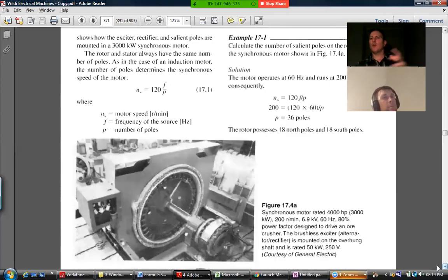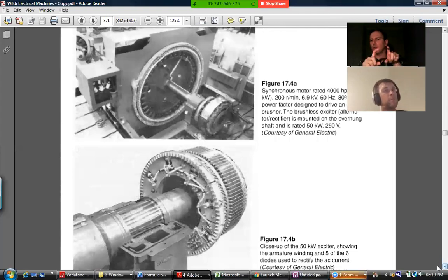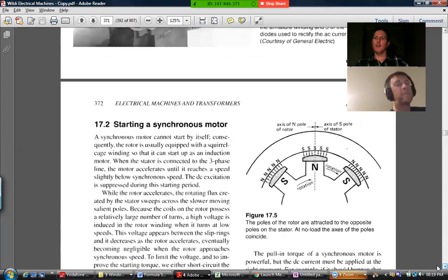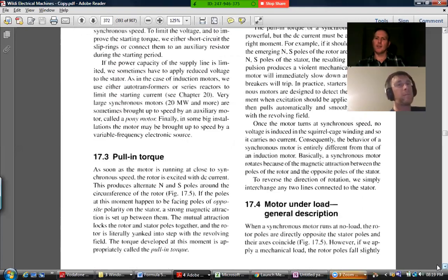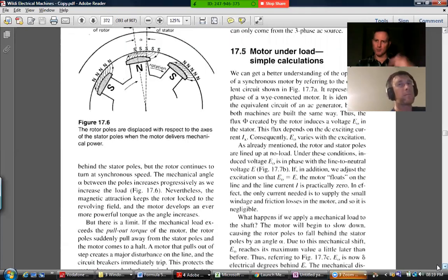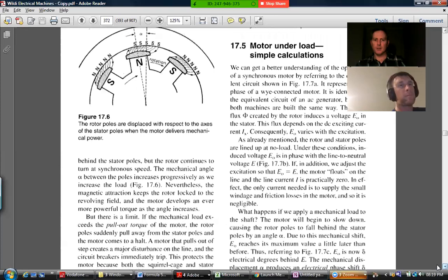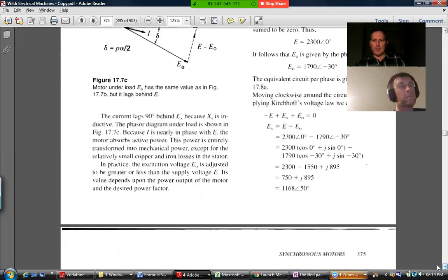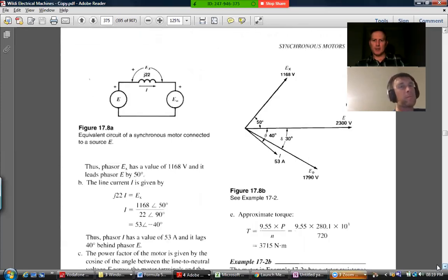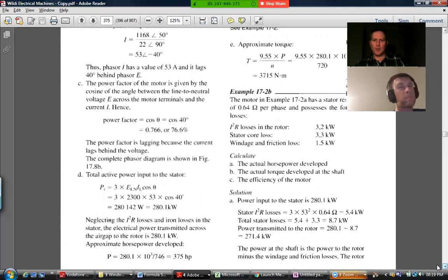Most small synchronous motors will just have 2 slip rings ready for you, and you just feed your exciting current directly into the slip rings. That's the same as the one that we've got on campus. There's no mini generator inside there generating the exciting current for you while the thing's turning because it's a motor. So look through that one.